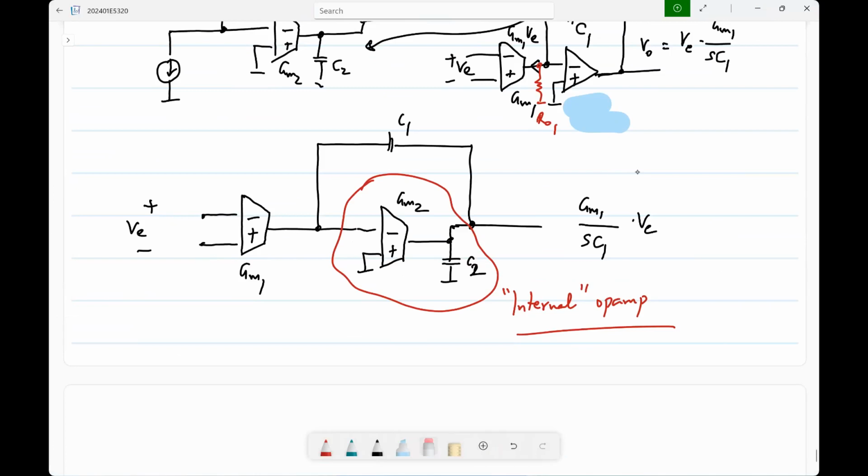Okay, is this fine? So essentially, you try to use negative feedback to improve this current to voltage conversion and result in a better op-amp. So now that internal negative feedback loop requires another op-amp, and you use whatever op-amp you knew, that single stage op-amp, to put there. Okay, is this clear?